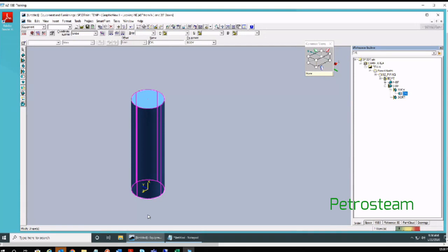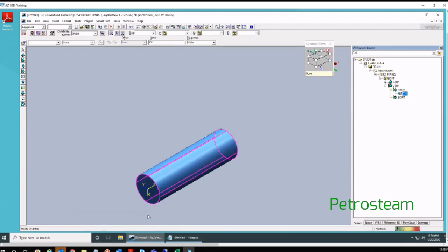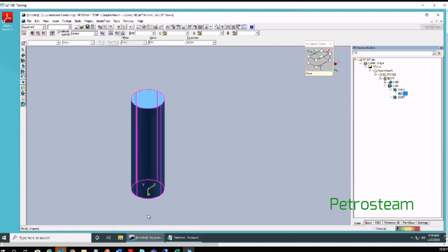Correct. Up arrow for changing the axis. Now you can see again using the up arrow mark, I am changing the axis. Now X is shown in blue. That means the X axis is activated. Now the Z axis is activated. Okay. I activated the Y axis for myself with the up arrow mark to change the axis. After that, using the right arrow mark, you are able to rotate by 90 degrees exactly.